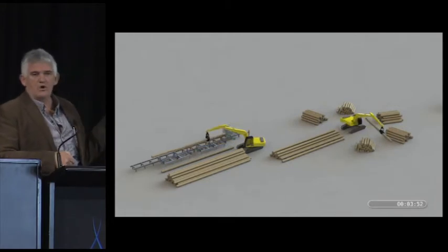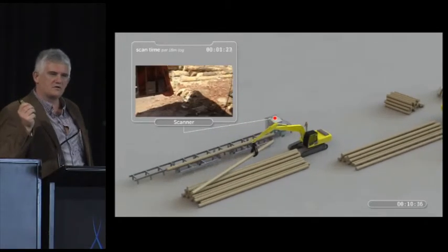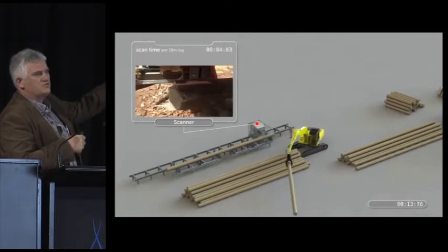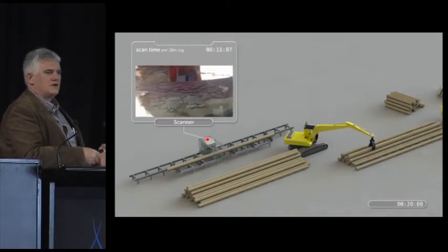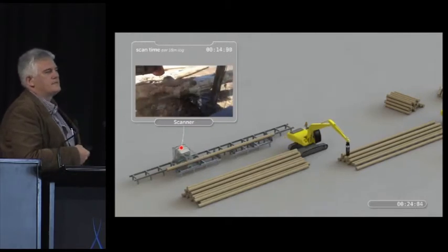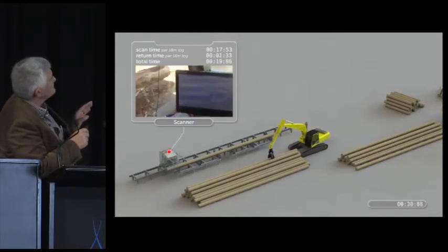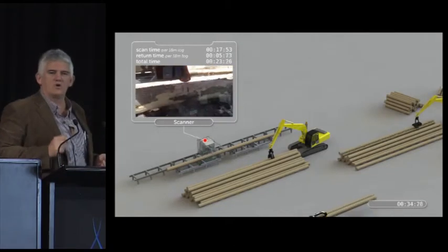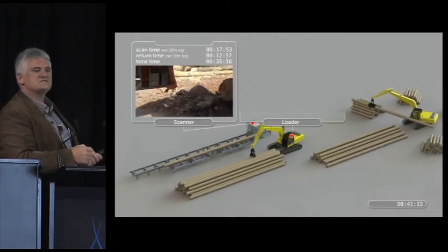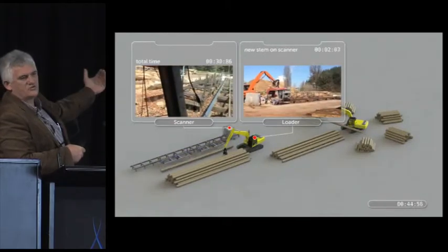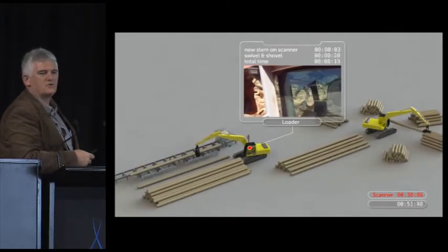So this is a model of the pan-pack type setup, very similar to what they've got operating currently. They've evolved this to another level. But these are the kind of systems that we have been involved in developing for our forests. So the fundamental process there, and quite different from the cutting up machine process, is that before a decision is made as to what log to make, our full stem features, diameter, length, deviation, have been assessed. We now use computers and the current market prices to say, every single tree, computer, tell me what is the most valuable mix of our logs.